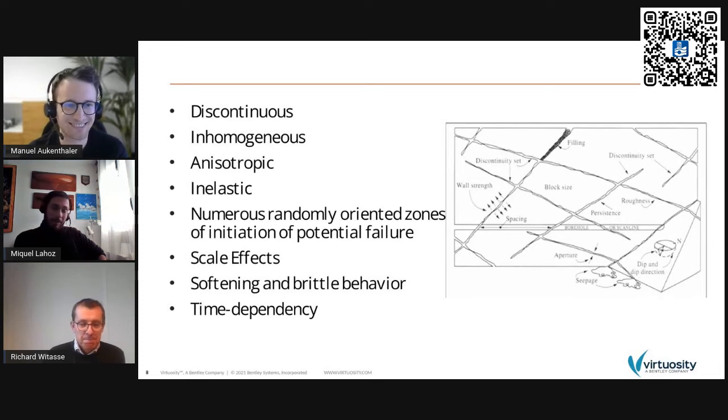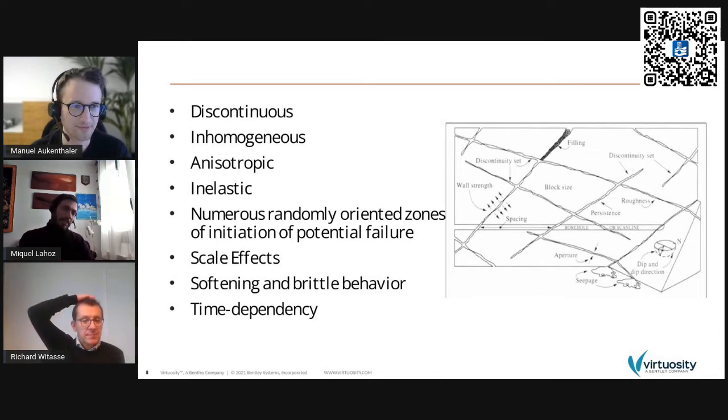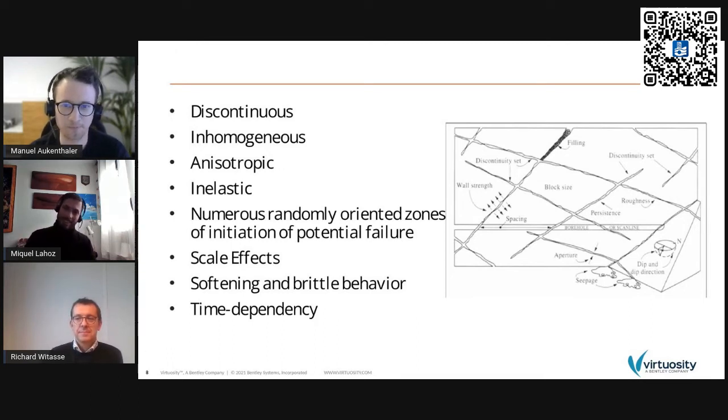Yeah, indeed. And we were talking before about solubility, and Richard talked about swelling. The most fun comes when you mix the two and you have a material that is swelling and soluble. So you go on the site, you assess your geology as no risk of swelling, but then you've got a water current that is transporting soluble minerals from upstream to your site, and suddenly your site starts swelling out of nowhere. Why? Yeah. Water. Sounds like big fun, and no one would like to have these kinds of surprises in your own project.